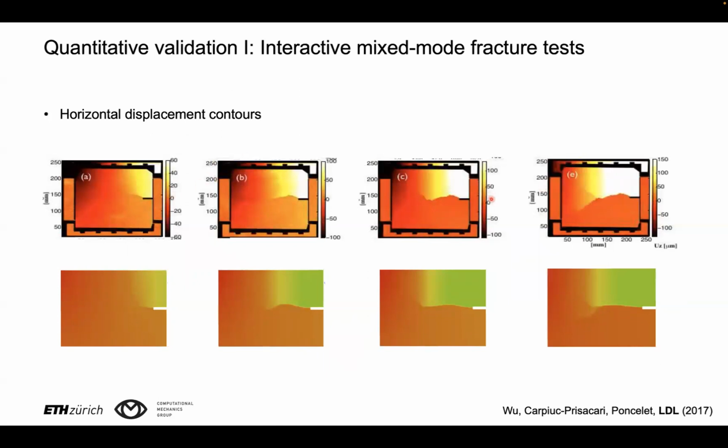And these all stably, corresponding to complex loading histories, which I will show you shortly. Here on the bottom row, you see the totally blind predictions of the finite element method discretizing the phase field model. This is a displacement field, and of course a discontinuity in the displacement, visible by naked eye, corresponds to the location of the crack. Again, the crack exactly reproduces the behavior seen experimentally: the first change in direction, the second change in direction, and finally the branching.